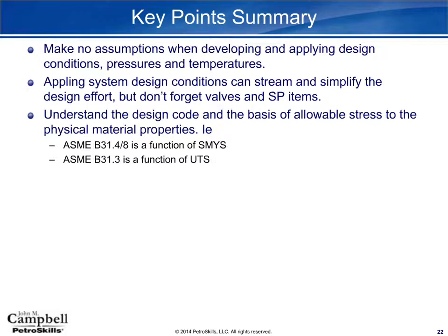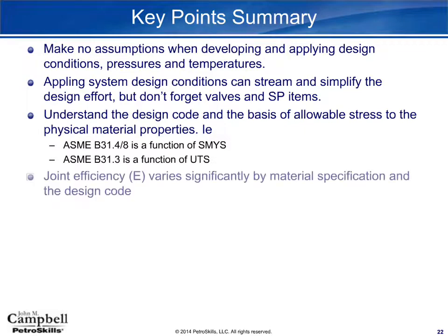Often the design strength on pipelines is a function of the installation stress, especially when we talk about subsea pipelines. The actual design and the limit on the pipe wall thickness may not be hoop stress, it may be a function of other stresses such as installation or longitudinal stress. Realize that the joint efficiency varies significantly by not just the material specification, is it seamless, is it ERW, but also the design code. Is it B31.3, is it B31.4? They are all factors that come in.